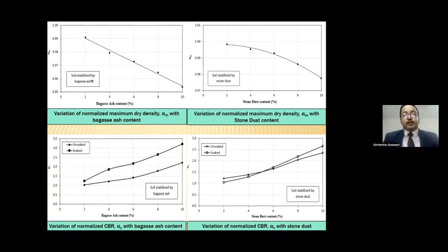These values of alpha m less than unity indicated a reduction in the value of maximum dry density due to addition of admixtures. This is advantageous in terms of decrease in the self weight of the subgrade with stabilized soil at optimum moisture content. The observation may be justified with the possible aggregation and flocculation of virgin soil particles with ion exchange between the admixture molecules, which has probably initiated a reduction in the weight volume ratio.